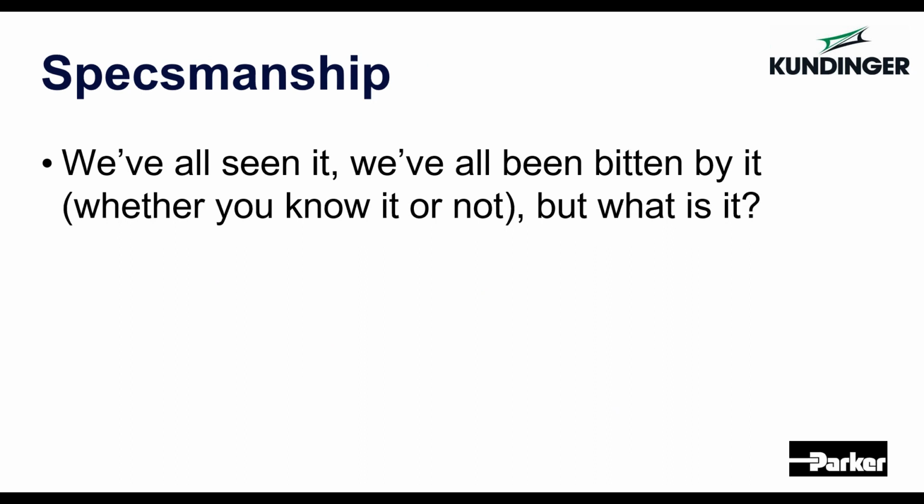Cross-sectional inertia. This is a pretty important one depending on how you're mounting these units. If you're mounting a unit down to a flat plate, you don't necessarily care about cross-sectional inertia. But if you need to mount a unit in an unsupported or self-supporting fashion, say you're just putting legs on the end, you're going to need to know how rigid the actuator is and how much deflection you're going to get. 2 reasons we care about deflection. 1, eventually we'll start binding up the bearings inside the actuator and the actuator is not going to move. And 2, how much deflection can you tolerate in your process?